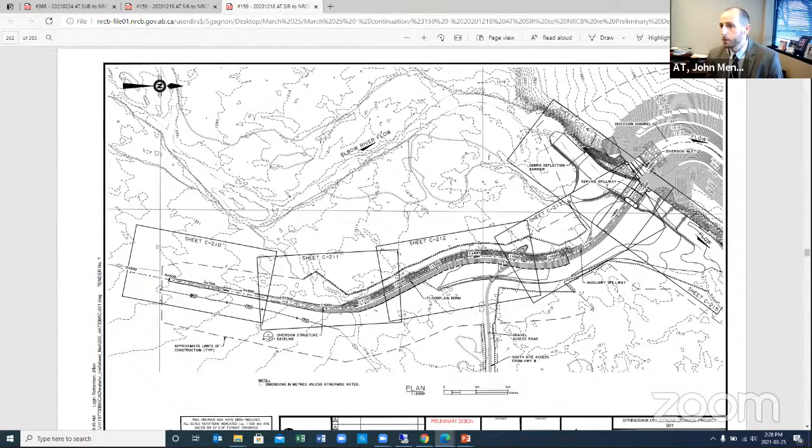At a very large flood, the gates from the service spillway would lower completely to the bottom of the river channel. At that point, the majority of the flow would continue through the service spillway structure. But if waters continue to rise, then they would overtop that auxiliary spillway and provide a secondary outlet.